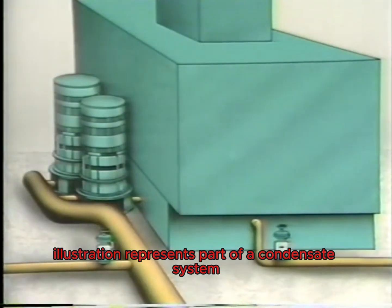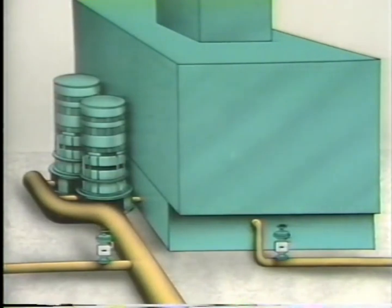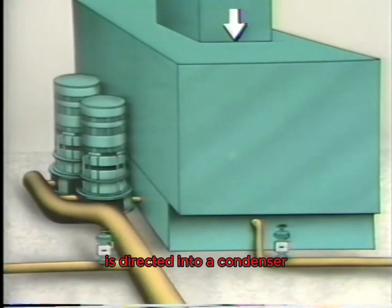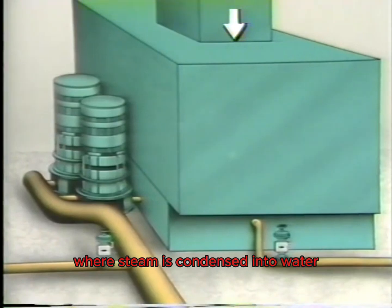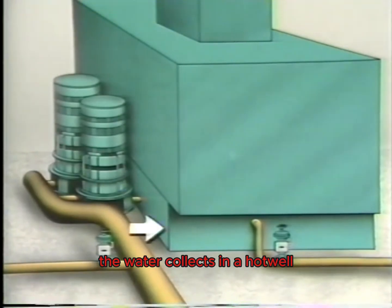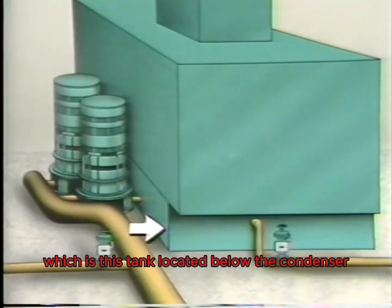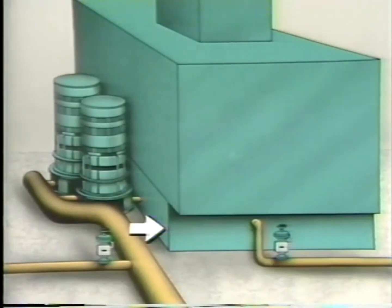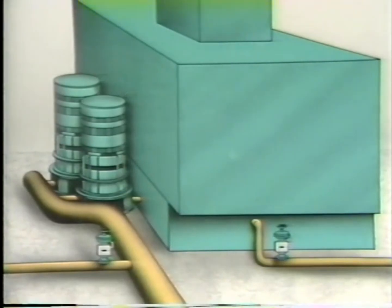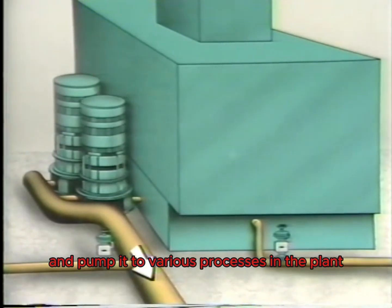This illustration represents part of a condensate system. In the system, steam that has been used in the plant is directed into a condenser, where steam is condensed into water, or condensate. The water collects in a hot well, which is this tank located below the condenser. 2 pumps draw water out of the hot well and pump it to various processes in the plant.